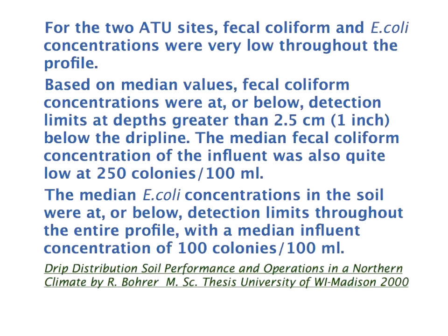Now, in the design done before with septic tank effluent, we can probably add a 0 to that 250 colonies, or at least I don't know if anybody else can type in what you would expect the fecal coliform count of a septic tank to be. I don't offhand remember that number. But anyway, it will be considerably larger. And maybe it'll take more than 1 inch. Maybe it'll take 6 inches before we're down to the background level.